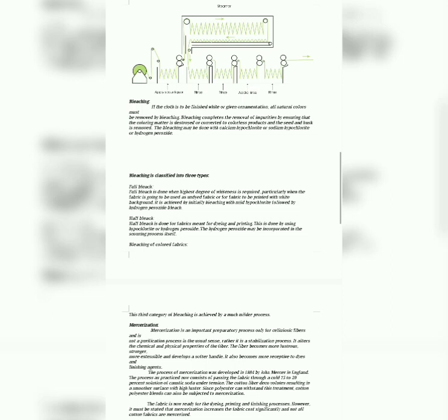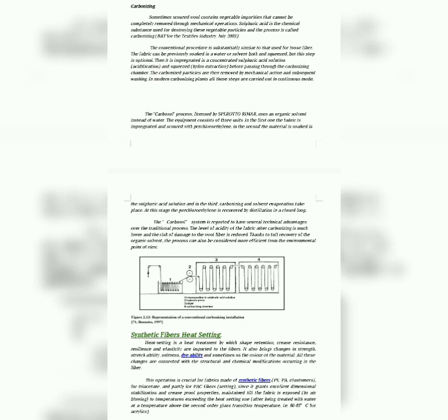Next, the step is desizing. This is the second process. Desizing is the removal of sizes, which are applied to the warp yarn of woven fabric to assist in the weaving process. The sizes make the yarn stick to each other, and thus the stresses present during weaving are shared more equally. Actually, desizing is the method of removing starches from the fabric so that the dyeing or printing stays for long.